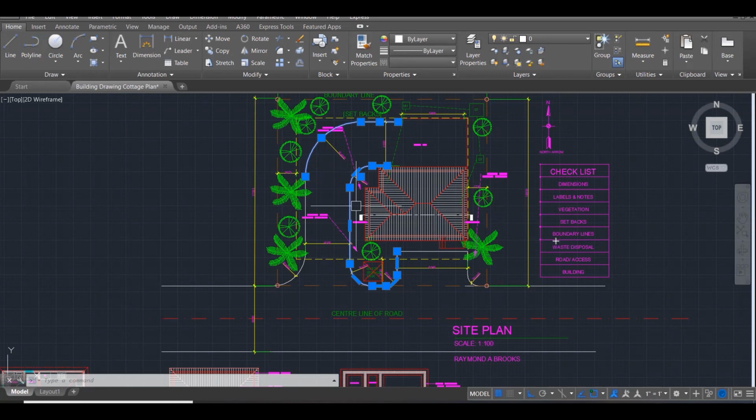Let's see what else here I didn't talk about. Oh, lastly, we have a north arrow, which gives us a lot of information. This tells us where north is. And if we know where north is, we're able to understand how the sun moves. And then we're able to understand where the coolest part of the building would be and where the hottest part would be. So let's just draw a sun ball here. And let me move this. We know that the sun starts in the east. That's where it rises. So here is the east. So this will be morning. East, I'll put morning.